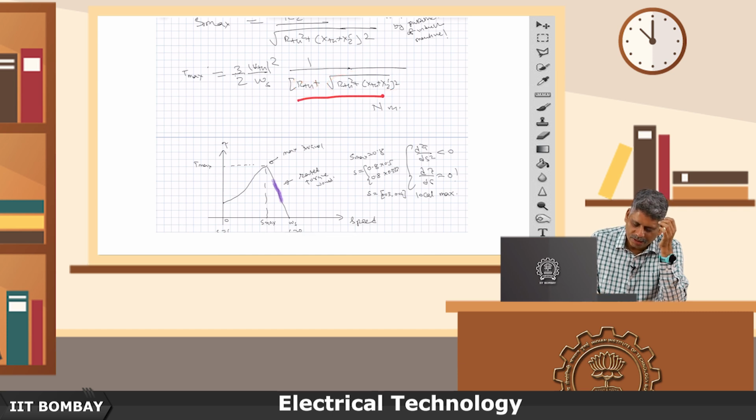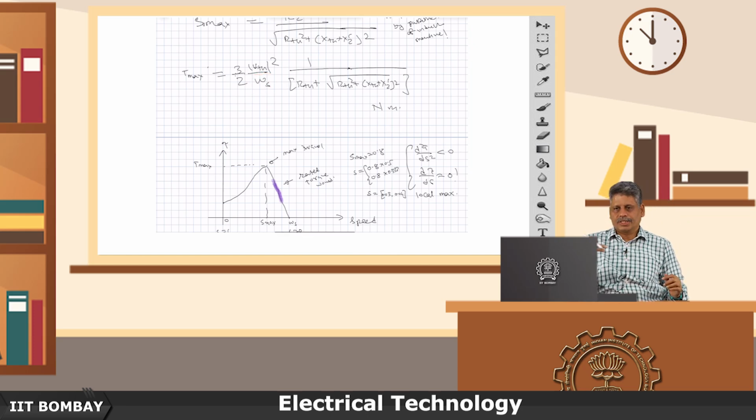So, the two quantities that are getting added here also have unit of ohms, and then V Thevenin square divided by ohms would give you basically the V square by R kind of unit, that gives you watts, but then you are dividing it by the speed. So, that gives you the unit of torque.